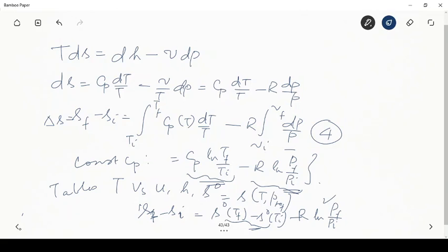And for internal energy and enthalpy change, since U and H are listed in the tables, you can directly evaluate them. You also have U, H, and S naught given as polynomial functions of T, or sometimes T by 1000, depending on whether it's expressed in joules or kilojoules. So then you can evaluate U, H, and S given the value of temperature. Instead of looking at the tables, you can use this. If you have a computer program that needs to evaluate it, you can use these.